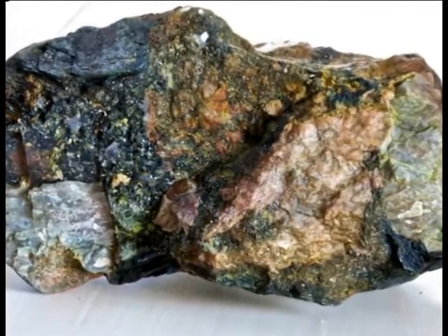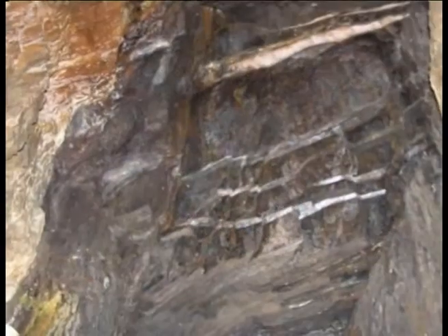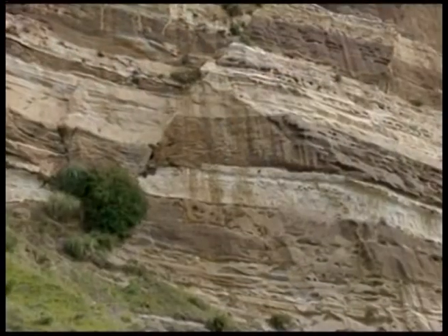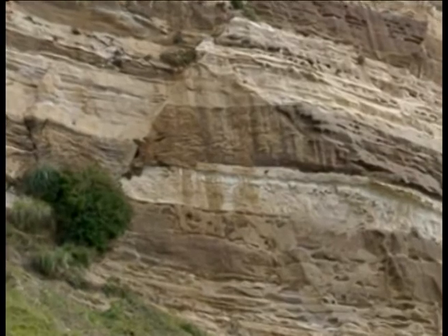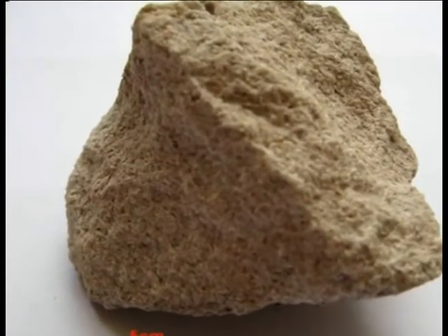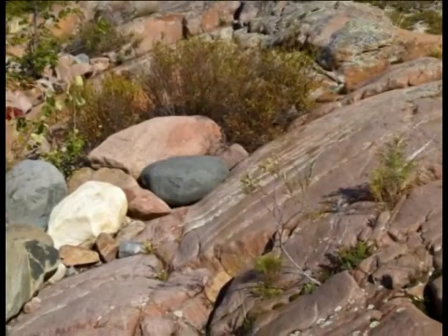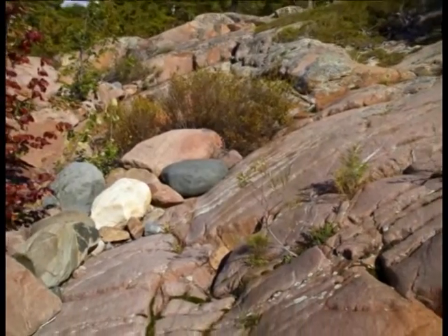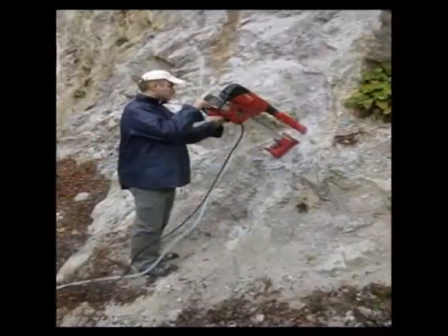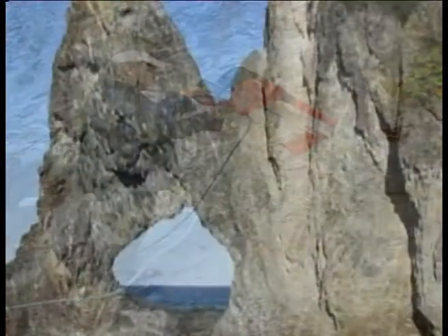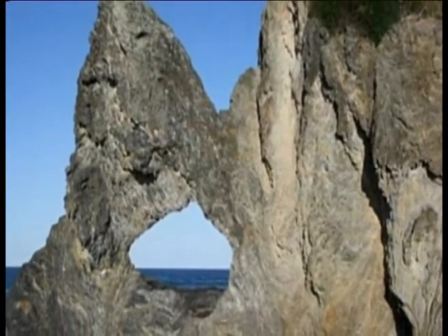The tensile strength, that is nothing but the pulling strength that has to be applied to a material to break it, is measured as a force per unit area. The direct method would require elaborate means to avoid bending while applying tensile forces by gripping the specimens at the ends. It is a very complicated process, and since the tensile stresses are seldom required accurately, an indirect method is commonly applied.